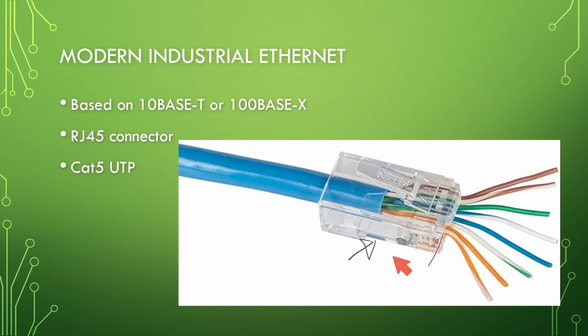I guess I didn't explain it very well to you guys, but when we were making our Ethernet connectors, I think I've probably explained it by now, but there were two different sections you were crimping when you used those crimping tools. The first was right there, and that crimping tool physically pushed that piece of plastic down into the Ethernet cable, so it actually smushed right there. And I told you guys that was grabbing on. You wanted your sheathing, the blue portion on this wire, past that point. So when you crimped it, that crimp grabbed onto that sheathing, so that was providing tension. That way you weren't pulling actually on the electrical.